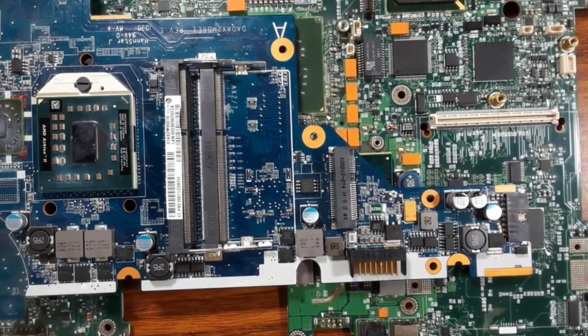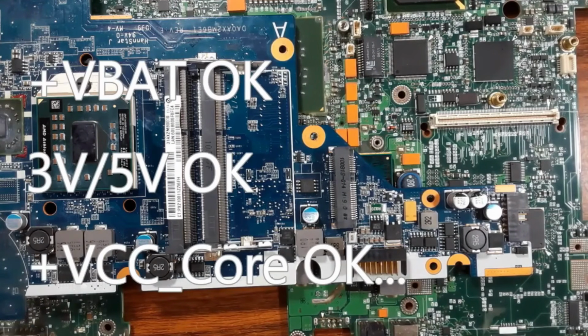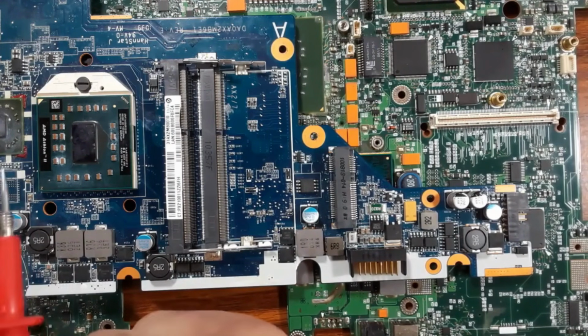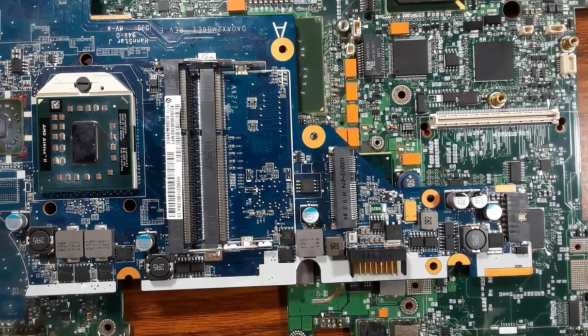The next failure is when you check all voltages in the motherboard, and you find that all voltages are present. You find the 19 volt, you find the 3 volt and 5 volt. Computer is on, all voltages are present. The 5 volt for the USB connector, the 3 volt present at pin number 8 of the BIOS. You find all voltages, but the computer still shows nothing on the screen, still a black screen or white screen.